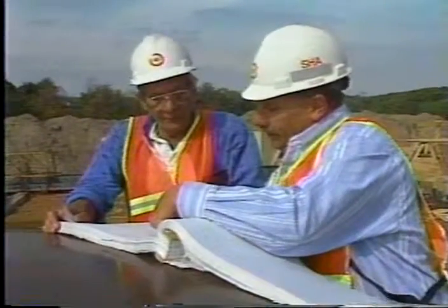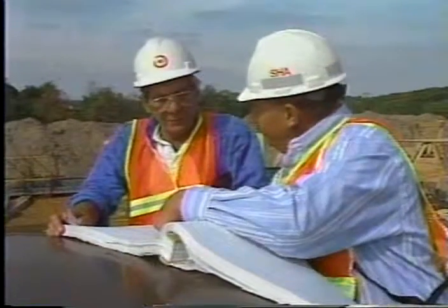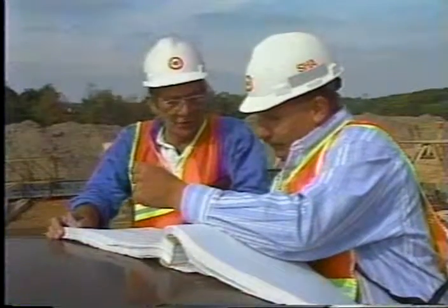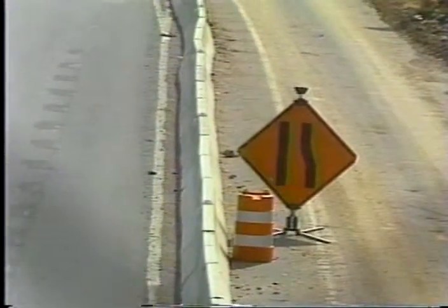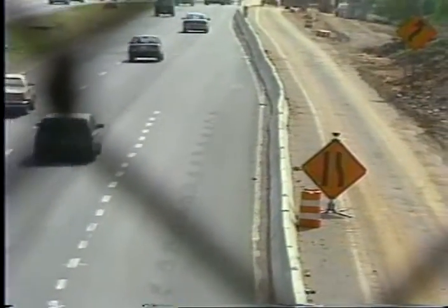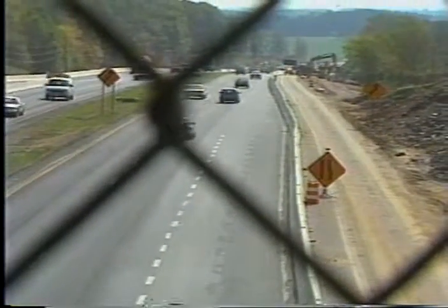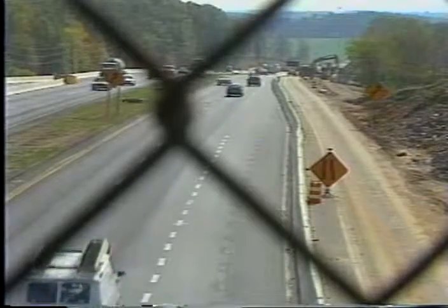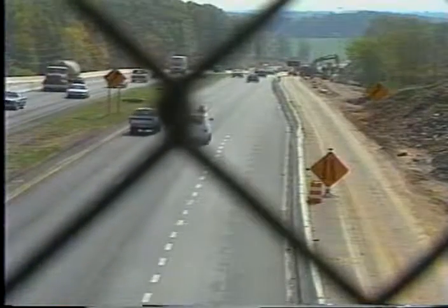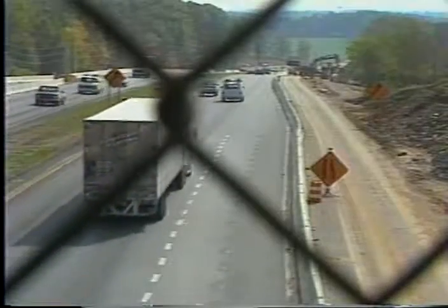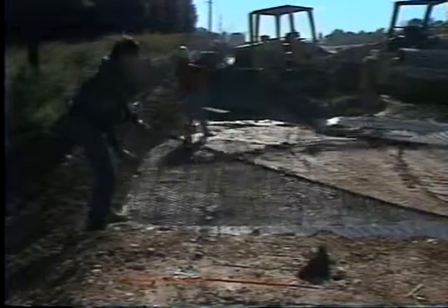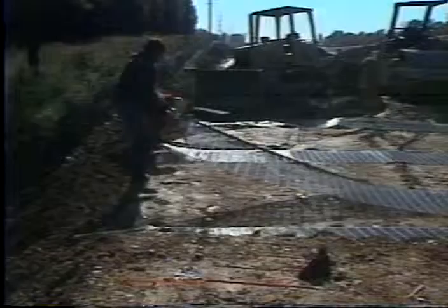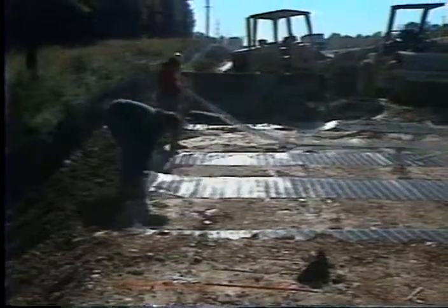For example, if asphalt paving is paid for by the ton, use tons. Roadway kilometer is the linear length of a roadway of independent or relatively independent alignment. Multiple lane, divided, or undivided highways are considered as two roadways. 7,500 cubic meters is a bid item quantity, which is used for earthwork inspection and testing on construction contracts.